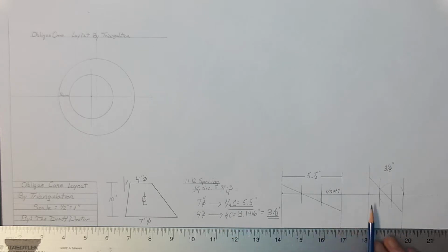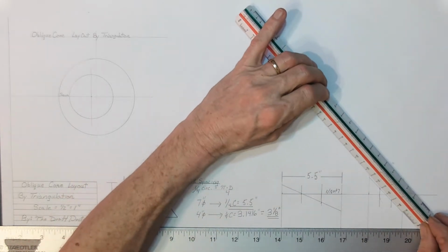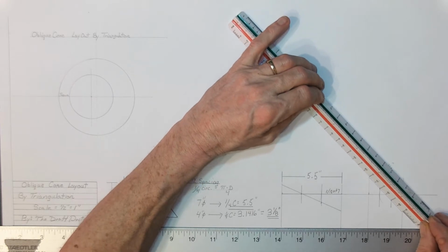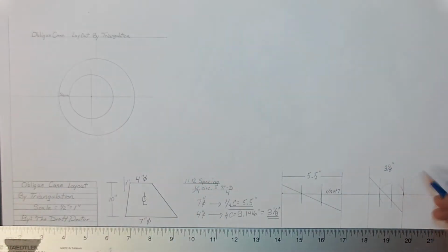For the 4-inch round I did the same thing. I laid out 3 1/8 inch lines parallel to each other. I used the diagonal. This time I had to flip to the 3/4 inch scale to make it work, and it doesn't matter what scale I use. Here's the 3/4 inch scale. I lean it over. I've got 0 there, 3 there. I mark 1 and 2, plumb them down to this baseline, and I have 1/12 of 4-inch round. So I got all my necessities in order here now.